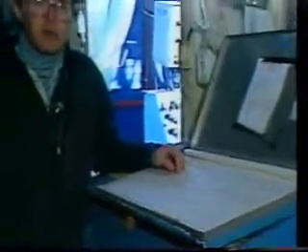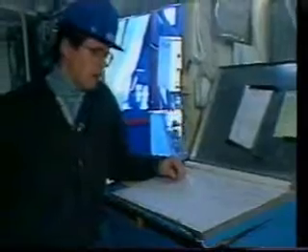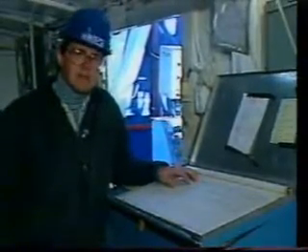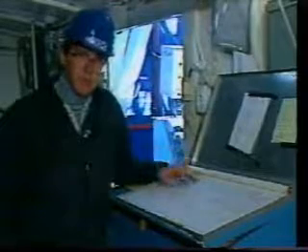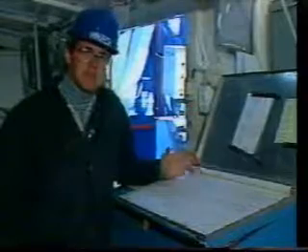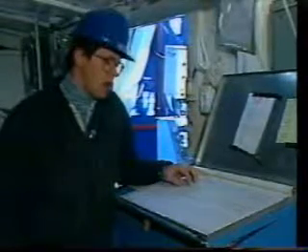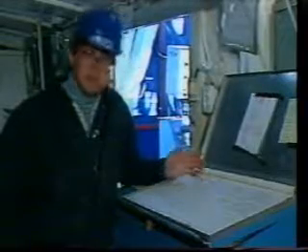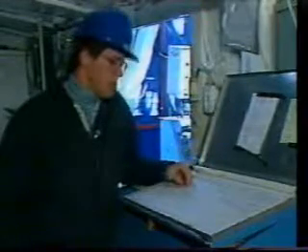There are a few other important things here in the doghouse. For example, this is the daily drilling report form that's kept current by the driller or the tool pusher. It's a complete log of all the activities that occur on the rig and the times at which they occur. It also includes important things like the measurements of downhole equipment, the mud viscosity and mud weight, the bits run, the type of bit and when, and notations of important safety drills.